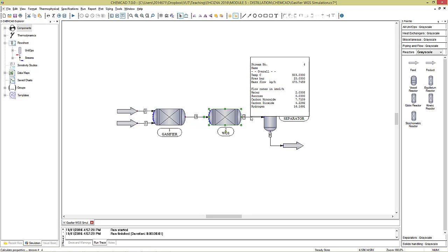Don't go below, because then you'll have excess carbon monoxide, which I would not really want to end up with in my reaction stream. I'd rather prefer to end up with excess hydrogen in my stream, but you don't have to worry about fine-tuning it to be exactly 2. Just get it slightly above 2, that will be fine, because again, remember, the methanol synthesis reactor is not going to be a 100% conversion reactor.